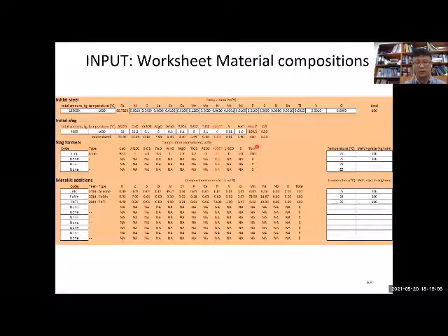After that, we just do everything as a prediction from the thermodynamic calculation. So this is the input we typically provide for our company. This is the amount of steel and the chemistry. You have the initial amount, in this case 165 ton, initial temperature 1600 degrees Celsius. This is the initial steel chemistry. We are not doing pure iron. We have aluminum, carbon, calcium, chromium, copper, manganese, all the impurity elements. And this is the initial slag, about 5 tons of slag at this temperature with a different chemistry here too.